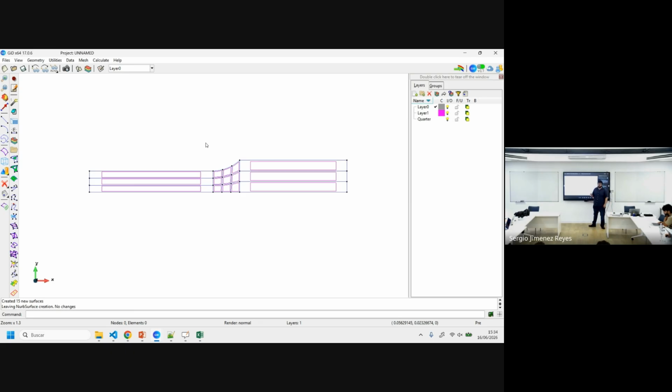They also have dog-bone samples, but the central area, this reduced width area, is not that long. But there are also other kinds, which are the hourglass kind of samples. And the point is that in these samples there is also some geometrical effect. But because we continue imposing the displacement or the force, the stresses and the nonlinearities are more or less homogeneously distributed in the entire width of the sample, and this geometrical effect is not that important.